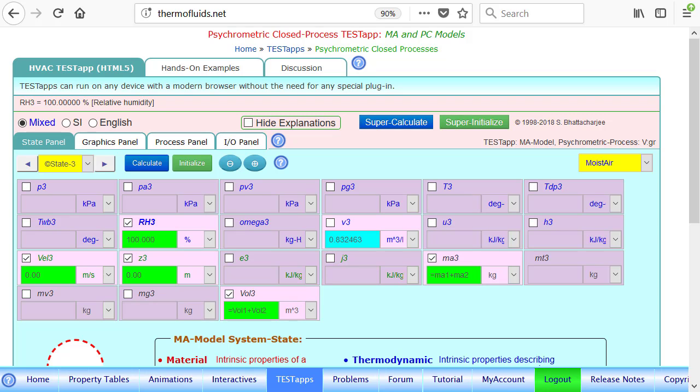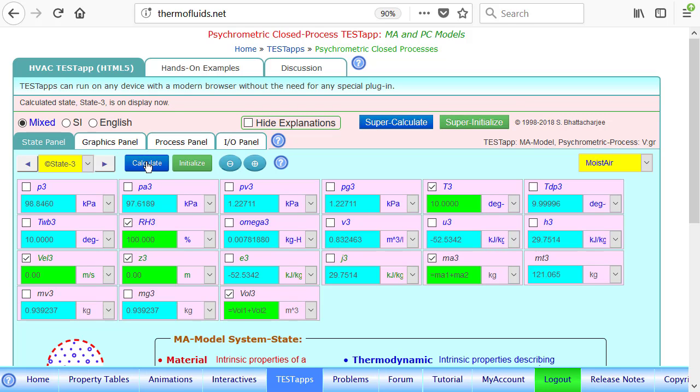What is the closing condition? That the final temperature should be such that there has been no heat transfer. Just suppose we arbitrarily pick a temperature. I just want to give an example. Suppose we say the final temperature is 10 degrees Celsius. It's 5 and 20, and our guess is 10 degrees Celsius is the final temperature. We arbitrarily decide. Of course, then we can find the state, the final pressure, and all the other quantities. With that belief, if we proceed, it's obviously an iterative solution.